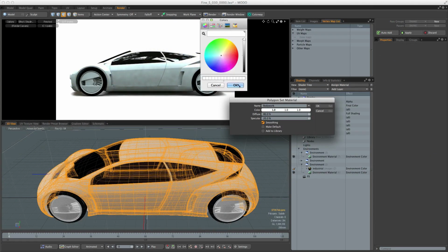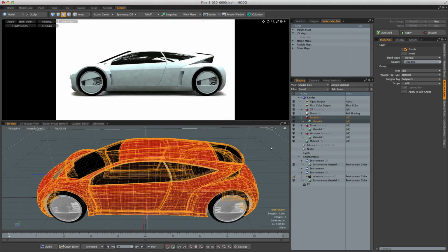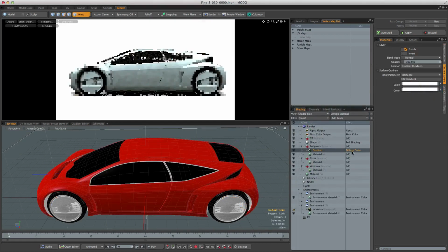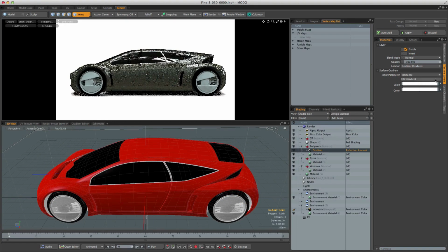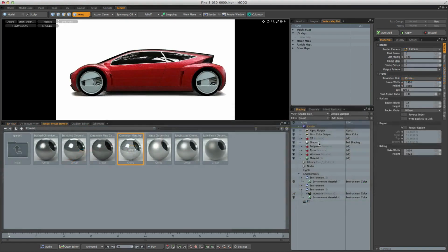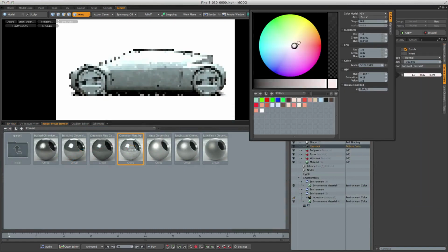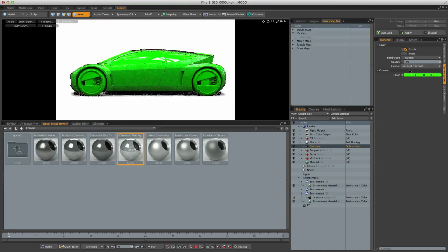The shader tree is a layer-based shading system that is built up by tagging aspects of your scene, and these tags become masks. Within these masks, you can then build up your materials from a wide range of material layers. What's interesting is even with these masks created, the shading is still decoupled from the scene, allowing material layers to override individual or multiple materials in one go.